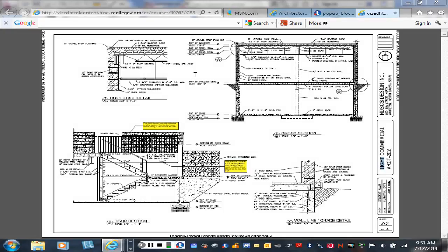So for the purpose of drawing your floor plan, let's assume at this point that our main level is going to be at 12 foot 8. That'll give us our roughly 9-foot ceiling height. And some of you may have decided to raise the center part of the building or even go to a 2-story, you'll have to create a higher level, obviously, right? So let's go back and look at our plan a little bit.